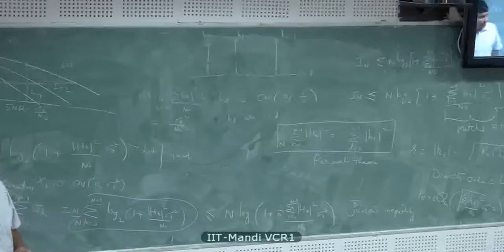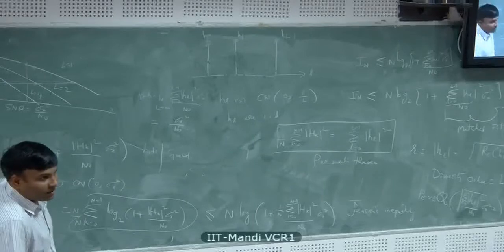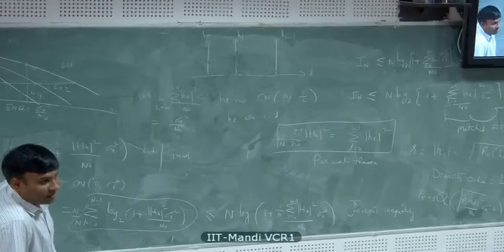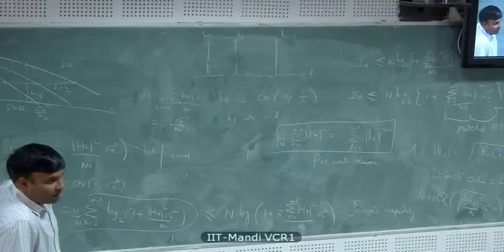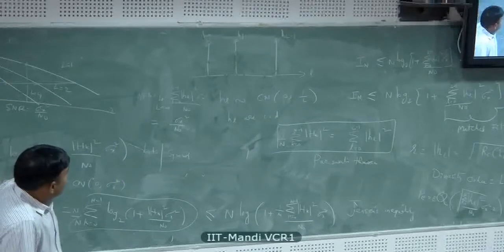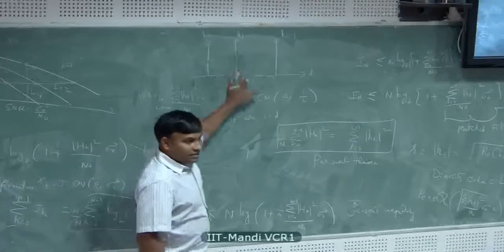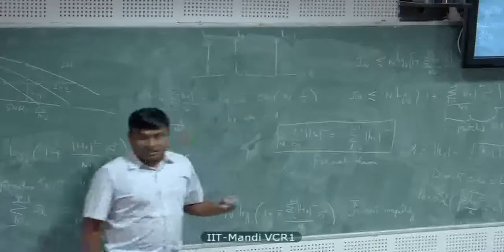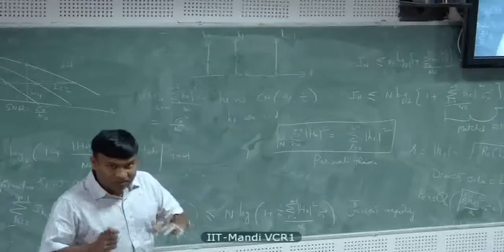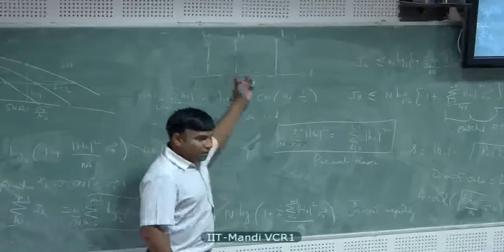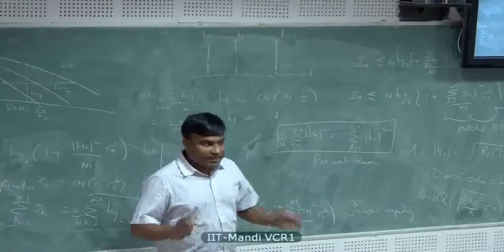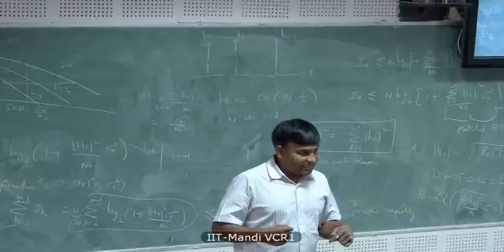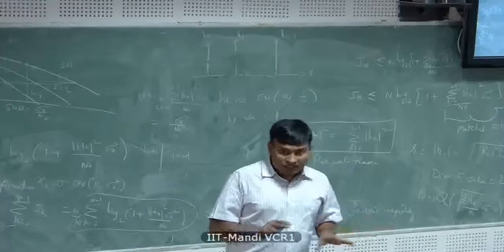So, as you said, we can control the diversity by putting more than one antenna at the receiver and the transmitter. Right. So when we have a frequency band in such a way that both H0 and H1 come into the picture rather than having a single tap. You mean a lot of multipath. Yes. In that case, if the propagation channel already gives you a lot of multipath diversity, there is no need for additional antennas to get diversity per se. There is no need for antennas.